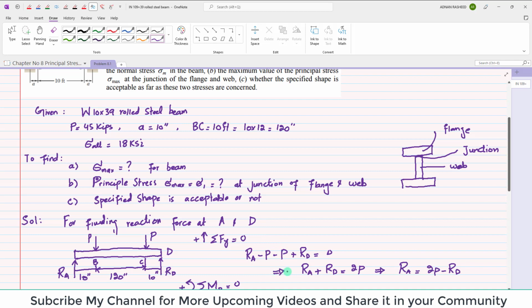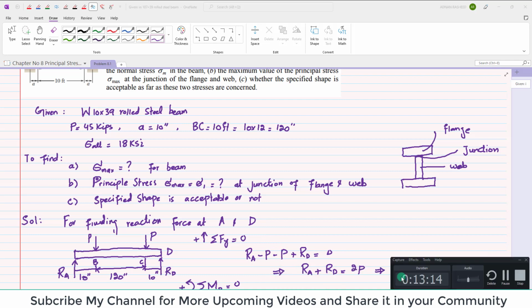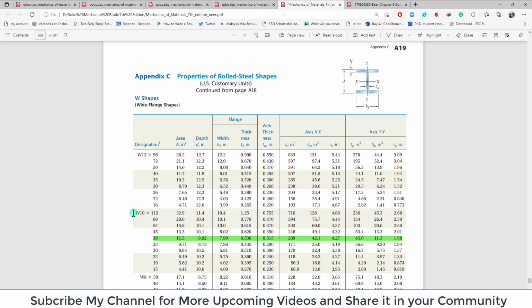So you can find its properties. Now you can see I have highlighted the W10 by 39. You can take the values of these properties. The height of the beam is D, which is 9.92 inch. The width of the flange is BF, which is 7.99 inch. All these values are given over here. You can see the section modulus SX is 42.1. So I will write these values over here.